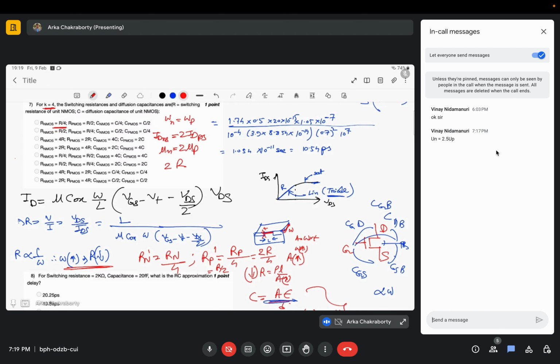Okay, so the exact value will be coming from the PDK, from the foundry, and just saying that it will be 2.5 times or 2 times is vague. It depends on the technology that you are using, and it varies from foundry to foundry because they change dopings and all. They use different substrates. Like GlobalFoundries will be using one thing, TSMC, Taiwan Semiconductor Manufacturing Company, will be using another, SCL will be using something else, and say IMEC will be using something totally different. Okay, so it is a good enough approximation to consider mu n to be twice of mu p. I hope it's clear, Vinay.